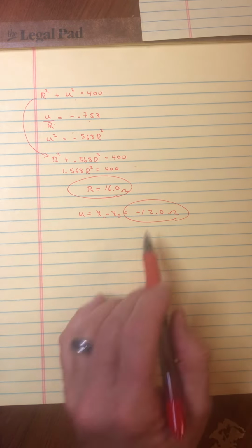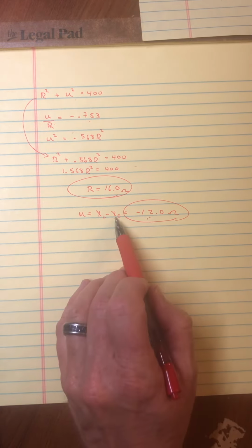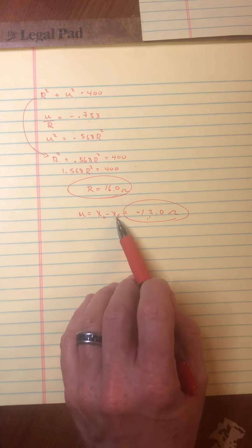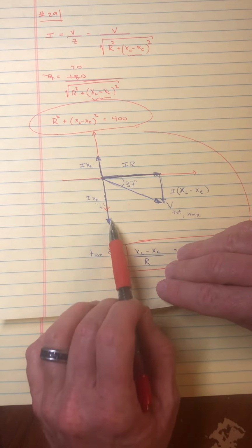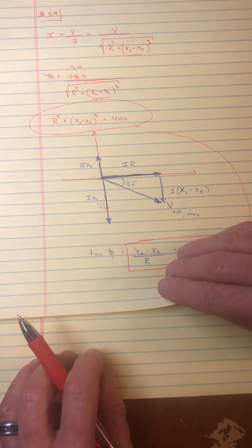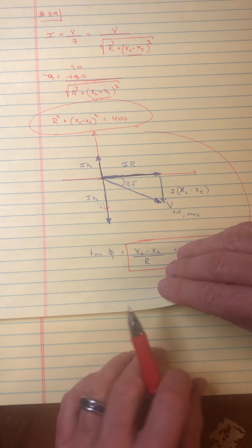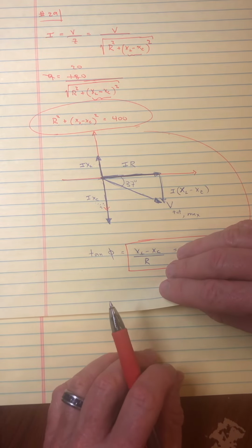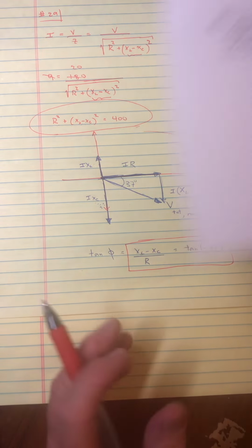And good, I got a negative here, meaning that the capacitor is stronger, which of course matches our diagram here, is stronger than the inductor in terms of this particular frequency, whatever frequency that is at, and they don't really say.